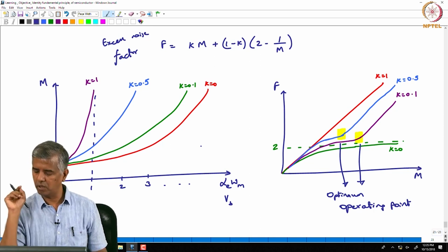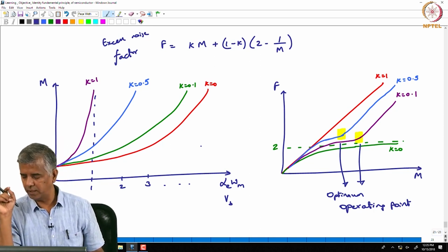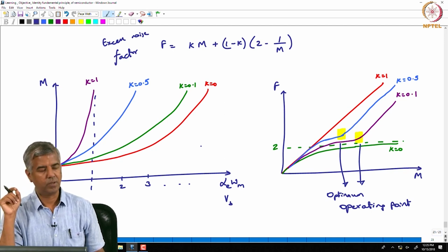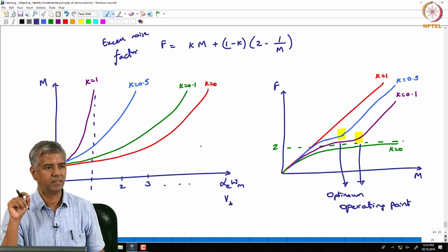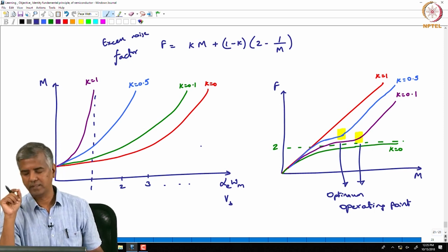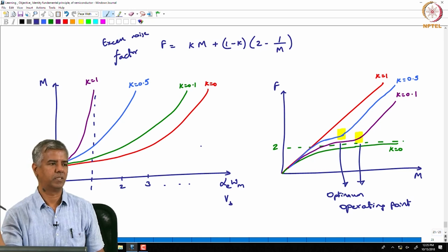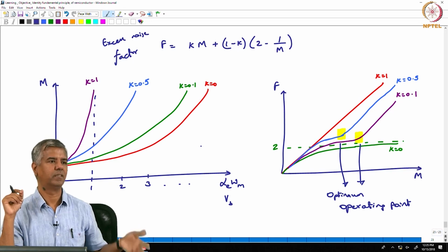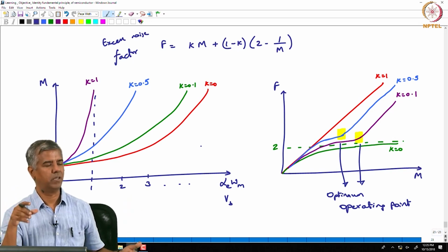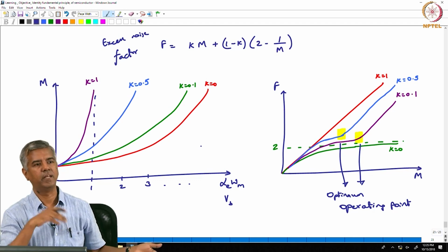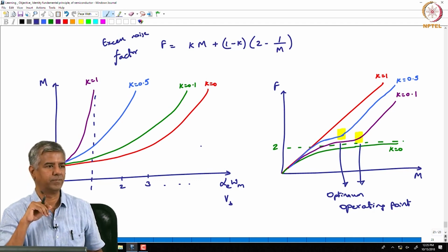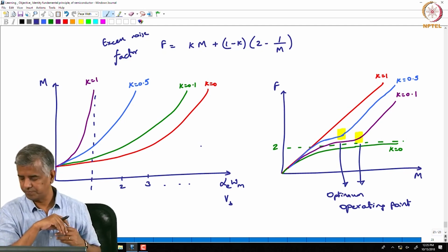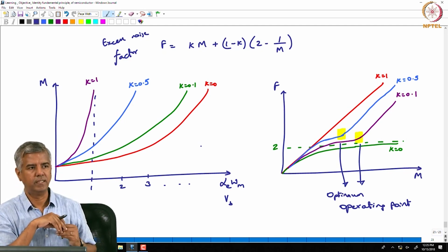It also tells you that the optimum gain you can extract from your indium gallium arsenide is going to be lesser than what you extract from silicon, just because indium gallium arsenide has a larger k value, closer to 1, than silicon. Okay. So, that is just a material property by itself. Do you understand that?